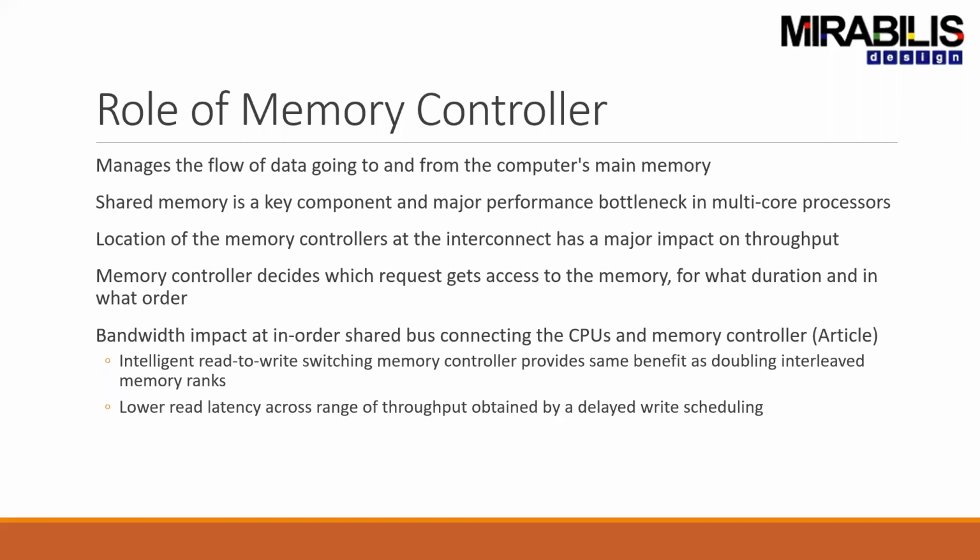The other one that is of importance is looking at how you can lower your read latency by delaying the scheduling of your writes. So you have a number of reads that are completed before your writes get started. These are all elements that are part of your memory controller architecture, and all of these have significant design constraints or bandwidth impact. Now, these are what we call the traditional elements of memory controller.